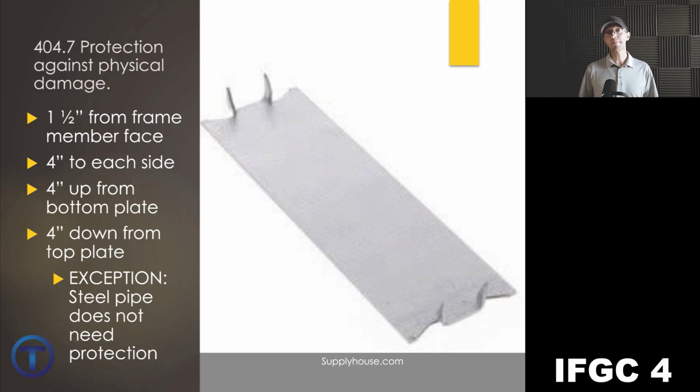404.7 talks about protection against physical damage. This is the same as any type of piping that we're going to install that could be damaged if a sheetrock screw or nail is put right through the side of the pipe. So what do we do? We nail plate, or we protect that. Now in the International Fuel Gas Code here, it says anything that's within 1.5 inches from the frame member face, so from the face of the stud in, if that pipe is within 1.5 inches, then it needs a nail plate. We also need to make sure it's protected 4 inches to each side, 4 inches from the top and bottom plates.